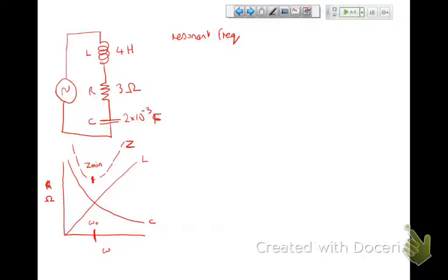And that's resonance, basically: when the driving frequency matches the natural frequency of the system, then you tend to store more energy. And that's what's going on here. You have a radio station which is driving at too low a frequency, and so my radio set, which has this natural frequency, ignores it. I get killed by the impedance. It's like I received the signal, but the current is so low for my circuit at that frequency that I don't do really anything with it.